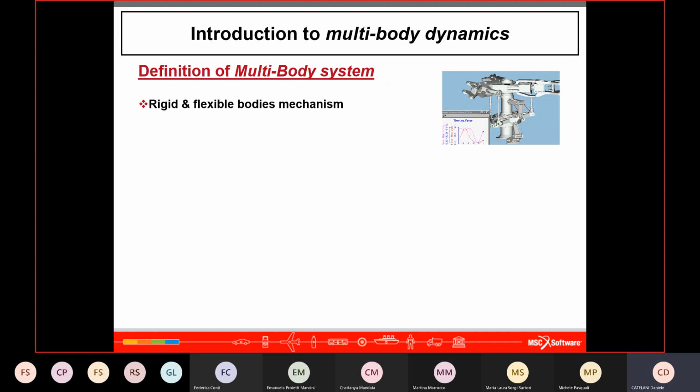In this case, you have a sequence of angles in order to uniquely orient the object in space. And you have to characterize the body with inertia data: mass, inertia, center of mass position, center of mass orientation. This is enough for the tool to describe the rigid body.